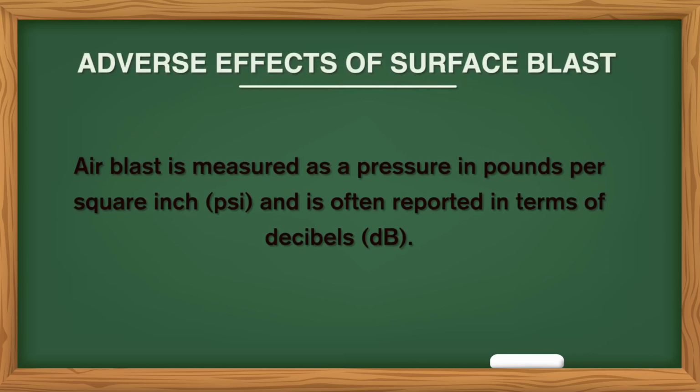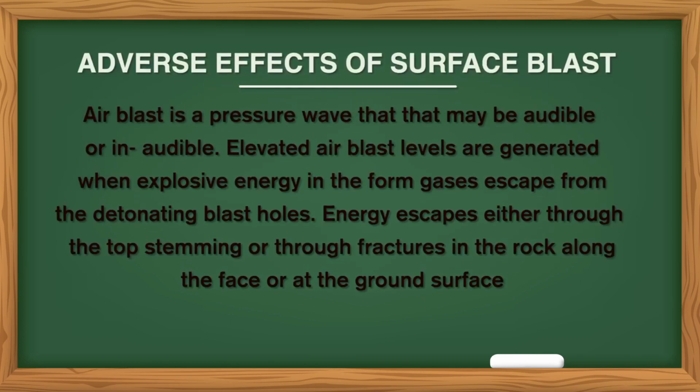Air blast is measured as a pressure in pounds per square inch and is often reported in terms of decibels, dB. Air blast is a pressure wave that may be audible or inaudible. Elevated air blast levels are generated when explosive energy in the form of gases escapes from the detonating blast hole.